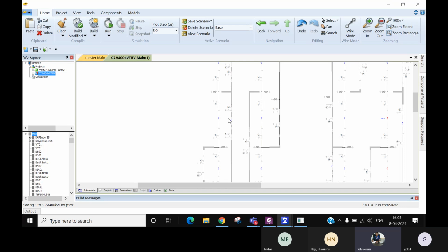That is TRV. Correct? Yes. Because this also assumes a worst case, where the voltage could be 2 per unit. Say 1 per unit voltage on the source side and 1 per unit voltage on the load side, but both in opposite polarity. Then you will reach TRV, meaning 2 per unit voltage TRV. That is like 400 kV times root 3, times root 2, times 2.